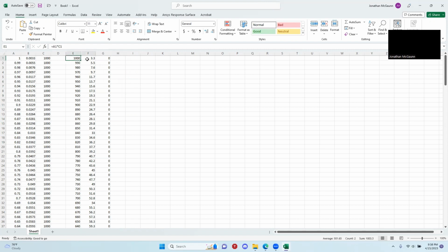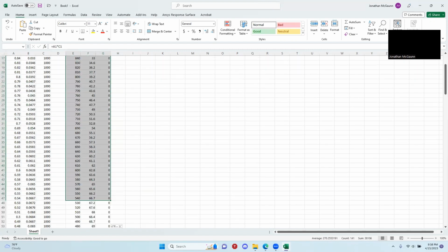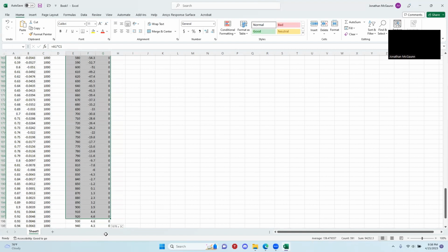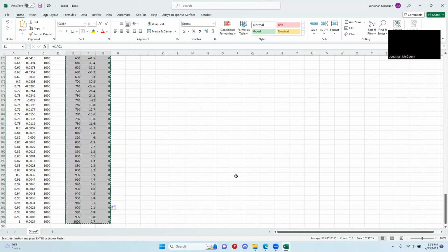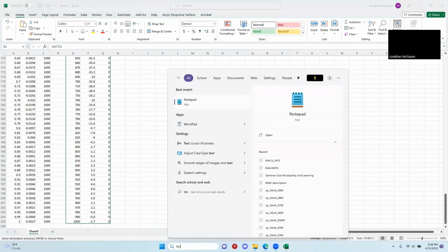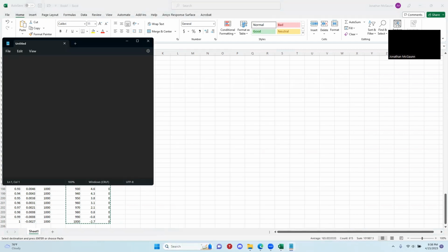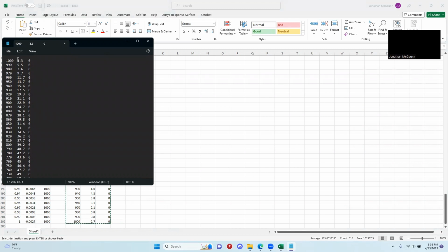So now that you're all set up, you can copy all of these. Open up a text file or a notepad. We'll just paste those values right in. If it looks weird, like say there's a tab here or something looks out of place, don't worry, SolidWorks is smart enough. It'll adjust for that and pick up the coordinates, no problem.